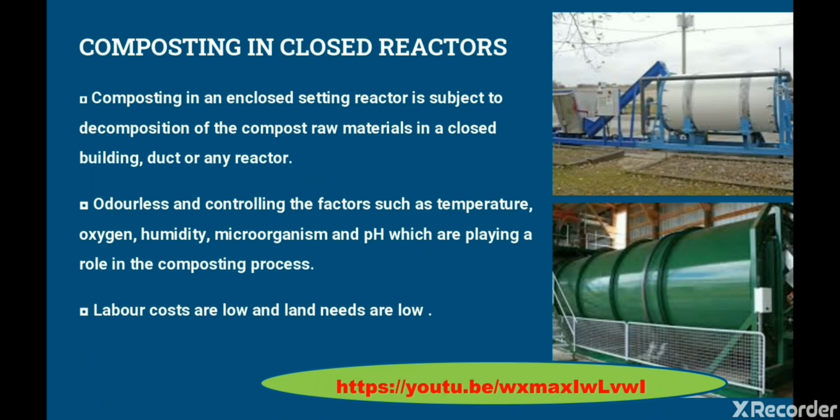Composting in closed reactors. Composting in an enclosed reactor involves decomposition of the compost raw materials in a closed building, duct, or any reactor. The reason for this is that it reduces odor problems and accelerates the process by controlling the factors such as temperature, oxygen, humidity, microorganisms, and pH, which play a role in the composting process. Despite the fact that the first investment cost is the highest, its use has increased in recent years due to the above mentioned features, and labor costs and land needs are also low.